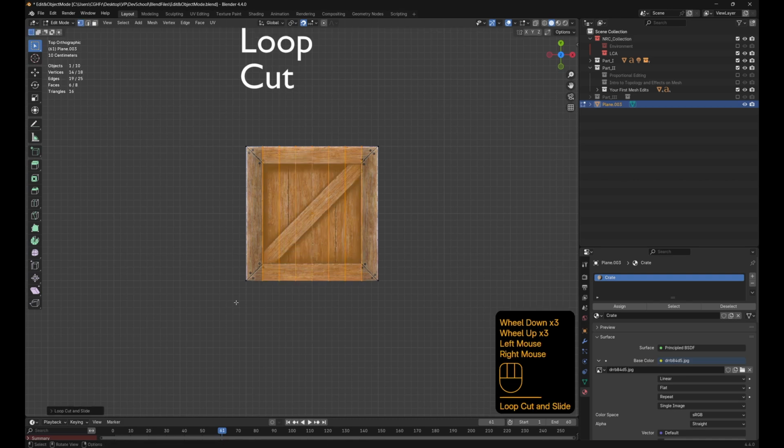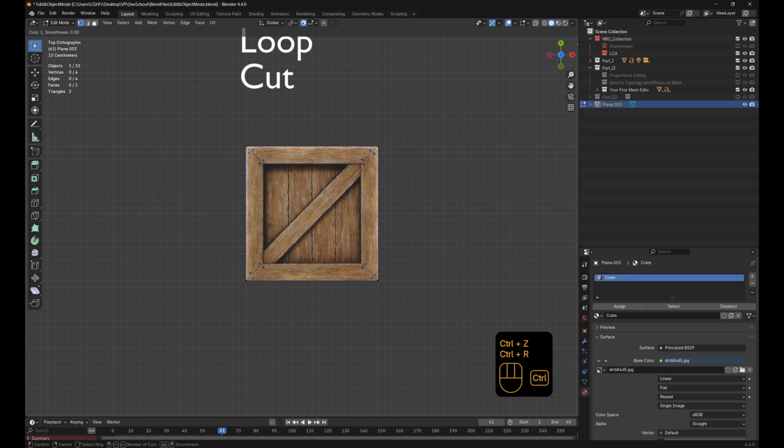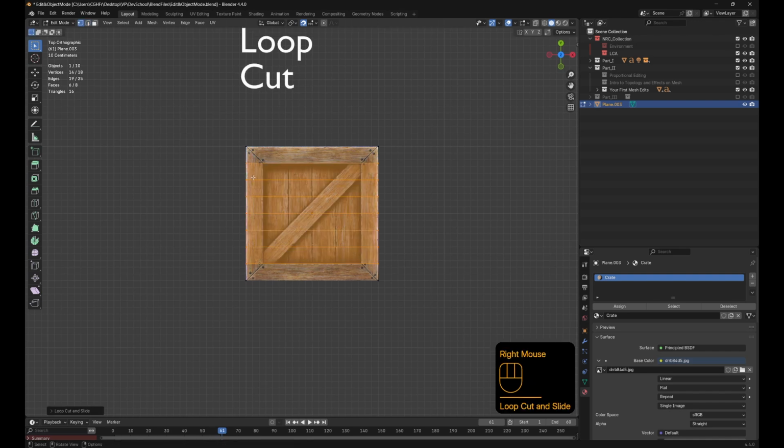That's about the right width. And once I've clicked, let me just do that again. Control and R, select a loop cut, add in a few. Okay, you can see I can't move them up and down the mesh. I can just select what side and which direction I want them going on. Okay, so we'll do here now. I can click once, and now I can slide them along that geometry, okay? And that's very useful. If I just want them in the center and I'm up here, I can right click and it will snap to the center, the median point of that face.